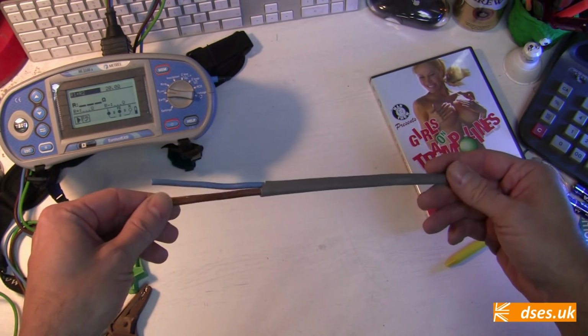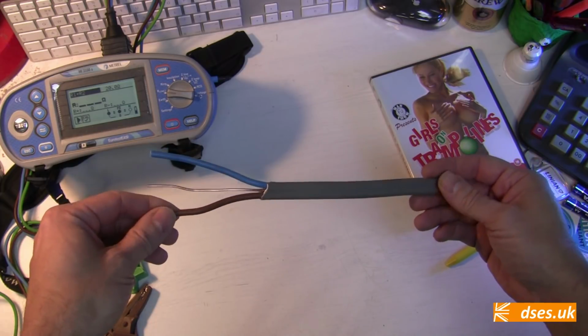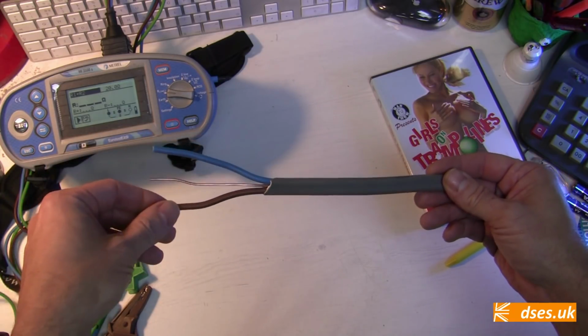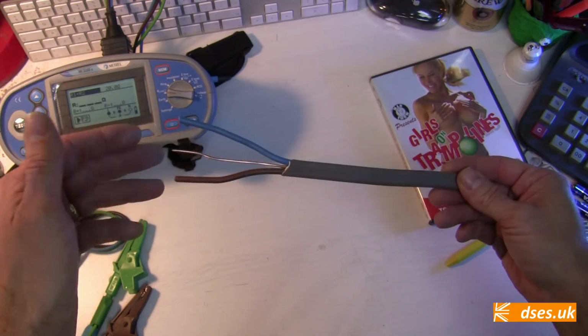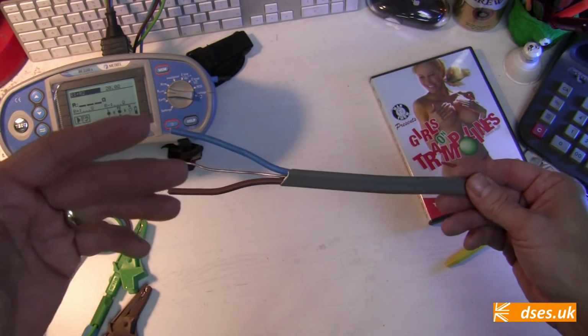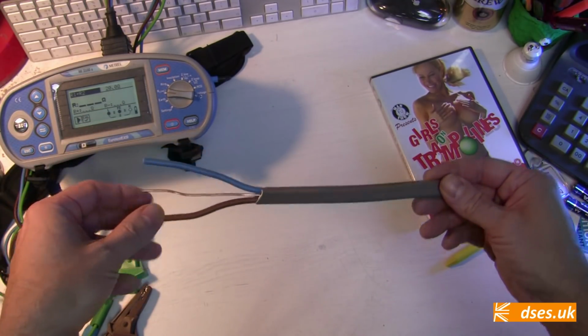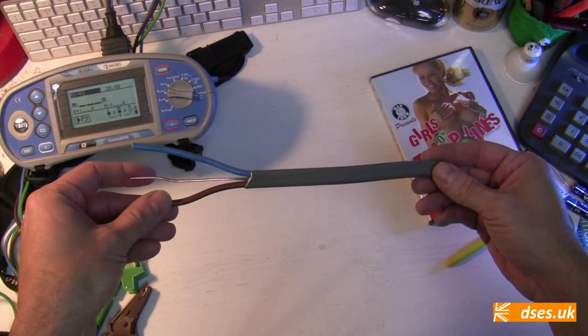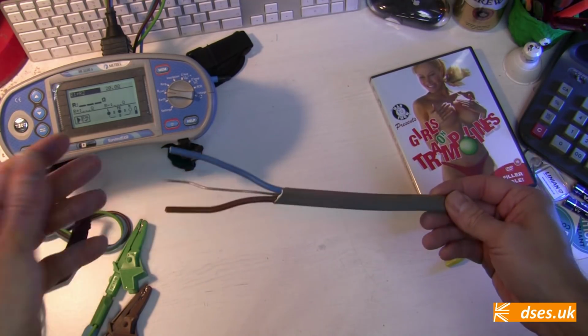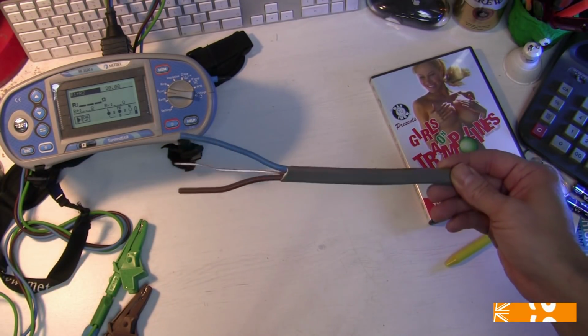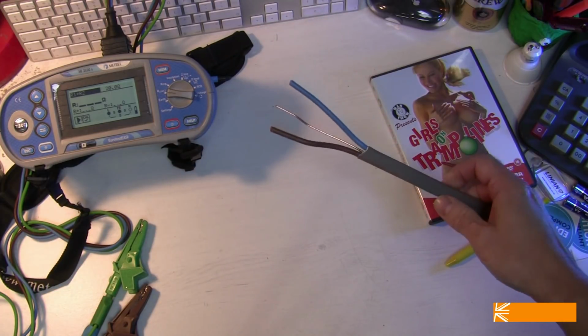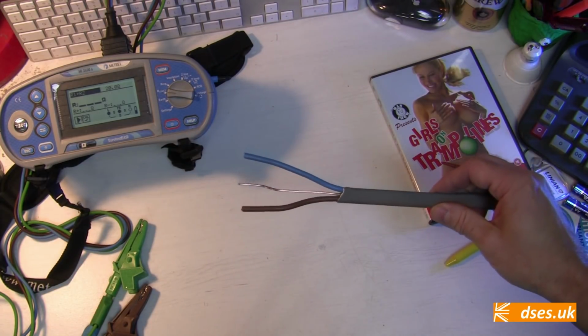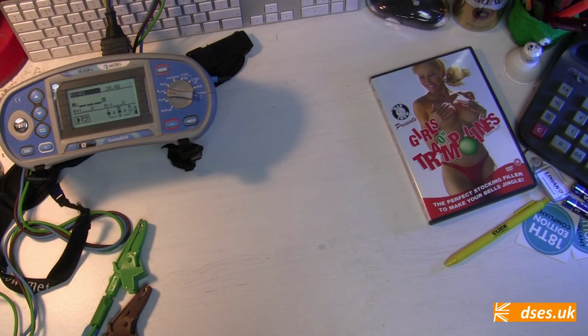Should that insulation be damaged or compromised, then it may be possible for current to leak from one circuit into another. We've already seen how a small current can form across an insulating layer through capacitance, but with an insulation breakdown, a much larger current can flow, and in the event of a breakdown to the point of a dead short, then one circuit can end up wholly powering another that it isn't supposed to. Allow me to demonstrate with the use of a demonstrator tool I have built specifically for the job.